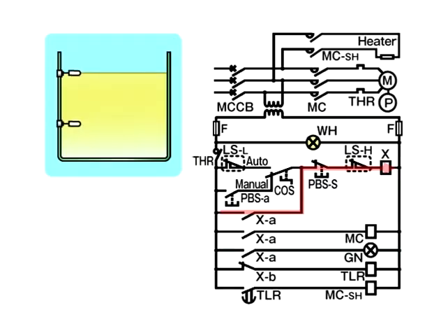If the pump operation continues, the fuel oil level rises. Here, the LSH float rises and the LSH relay turns off. Let's see how the sequence circuit operates from this state. When the LSH relay is turned off, current passing through XA, PBSB, LSH and to X is cut off, and the X coil is demagnetized.